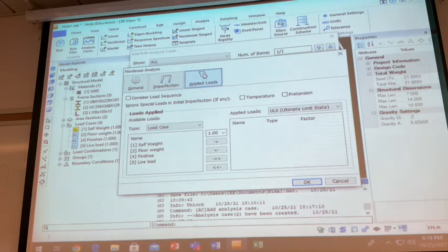So you also need to check the section capacity. It means that because the linear analysis hasn't helped you to check any geometric nonlinear effect or material nonlinear effect, you need to check this by yourself. So this is why you need the hand calculation. But however, when you base on the second order analysis, even if this is the second order analysis and elastic analysis, you don't need any design formula, or you can get it numerically, solve it from the program.